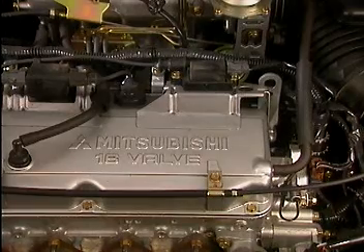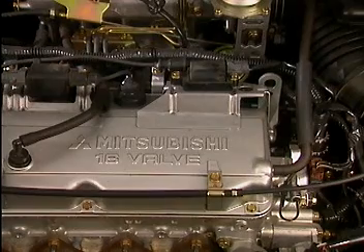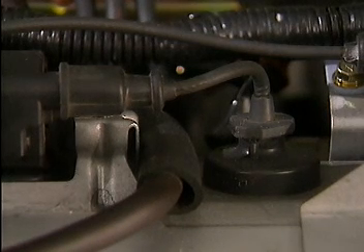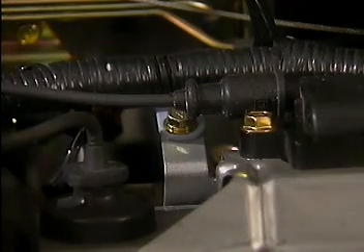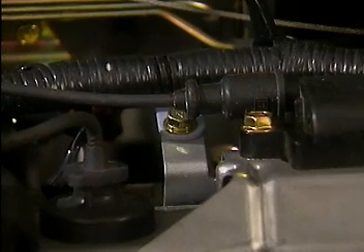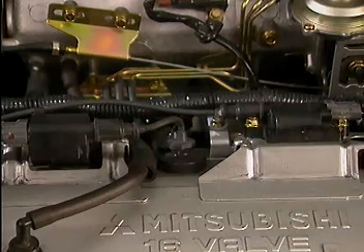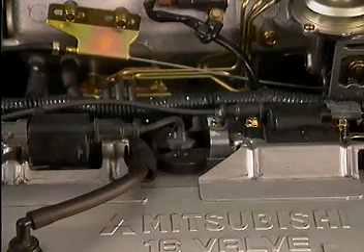The ignition system on the 1.8-liter engine has been upgraded. The ignition coils mount directly on the number 1 and number 3 spark plugs, and spark plug cables connect the number 2 and number 4 spark plugs to the secondary terminals of the ignition coils. This system simplifies the secondary wiring and makes it more reliable. The ignition power transistors are now built into the ignition coils.